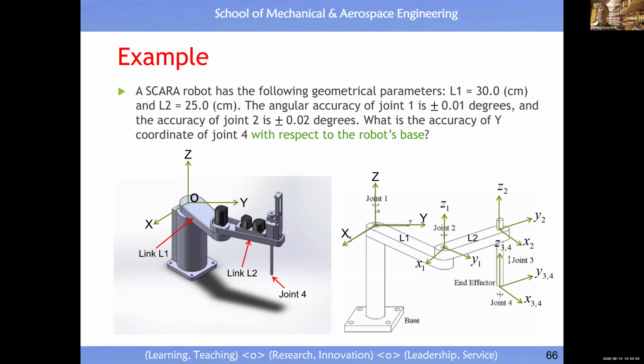we will use a speed reducer, right? When the speed reduction ratio is too small, then the output motion is shaky. You can reduce that error by increasing the speed reduction ratio. This example is for you to understand the relationship between the error at the tooltip and the error at the joint.